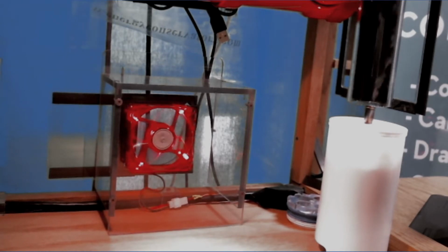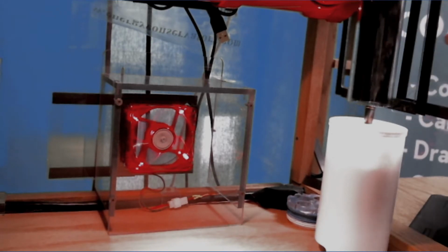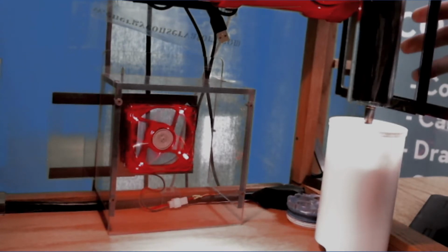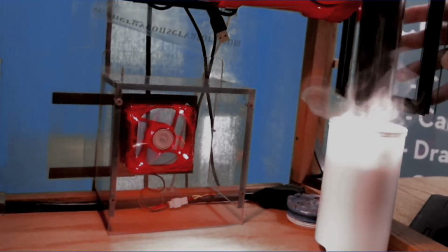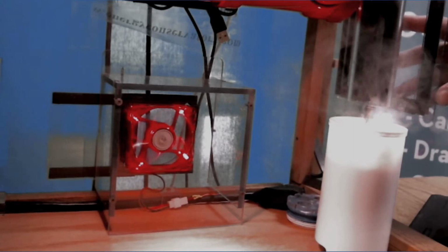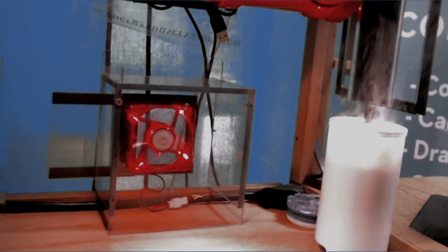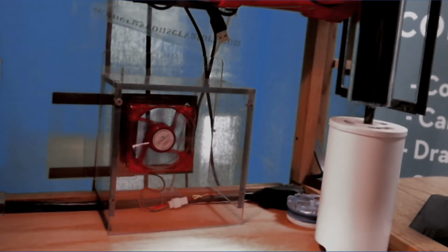And real quickly, you see how the smoke's going out the chimney. But if I put my hand here and start closing this up, depending on what's going on in the rest of the house, it might affect the smoke going out the chimney. We'll talk more about this later. I just want you to see how that can happen. Basically, I was tightening the house up when I closed that window, but now I'm going to open the window, and then you'll see the smoke goes back up the chimney. We'll talk about the pressures. I just wanted to give you a quick little demo of that, and then I'll go back out here.